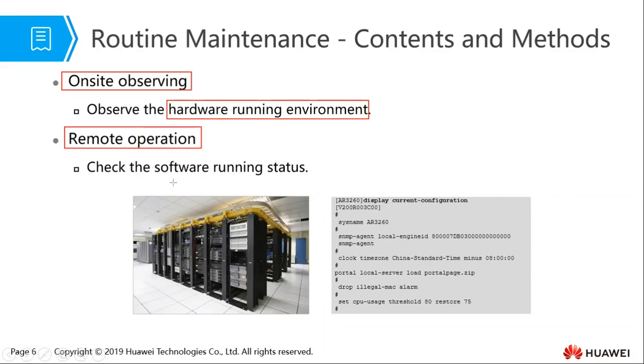You simply visit the equipment room, measure the temperatures, check the humidity, check the power cables, and check whether the physical modules of the devices are working, like the fans. You check whether the room is clean, whether we have dust or any other thing. Sometimes you'll need some professional tools in order to observe or measure some of these parameters.